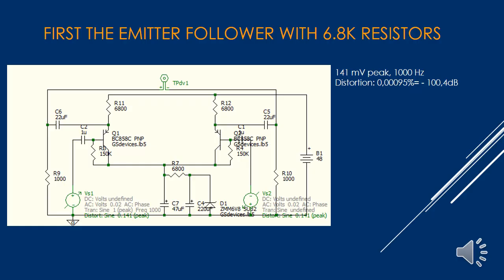Here you have the 6K8 resistor. Here you have the emitter follower. Here is the balanced signal coming in, and here it's coming out. And these are the blocking caps, and this is the input resistor of the microphone preamp. And then you measure the result of the output.